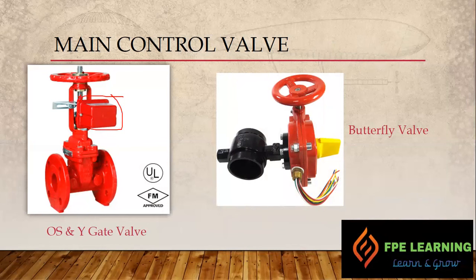So how are you going to identify whether the valve is open or closed? Because most of the time the failure of a sprinkler system is because of the closure of the control valve, because someone doing maintenance forgets at the end of the day to put the system back into service, right? It happens because most of the losses happen because of the failure of the sprinkler system. Research found that this is mainly because of the closure of the control valve. So if it is supervised, if someone is closing or opening this one, it will give a signal to the panel and a supervisory signal, and they will come and check what is happening.